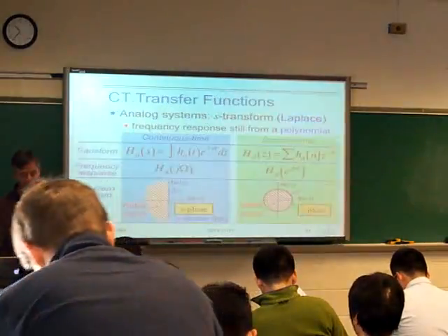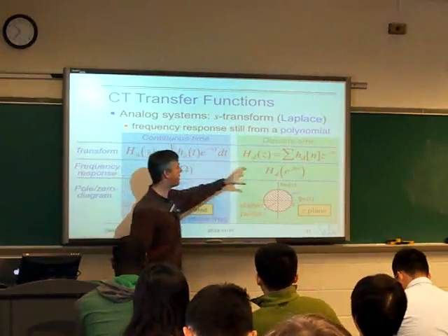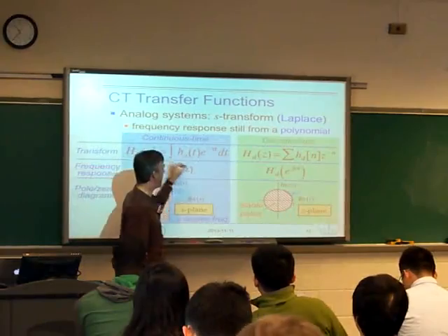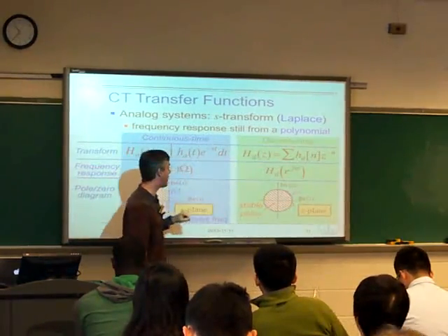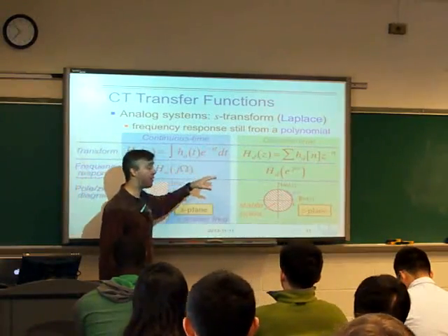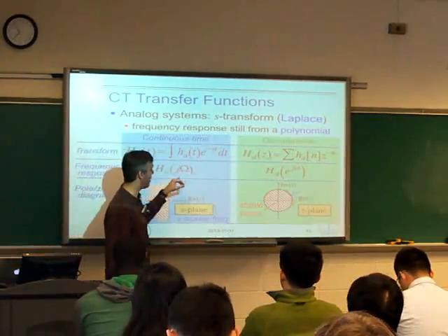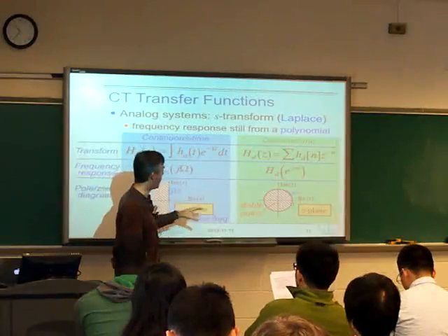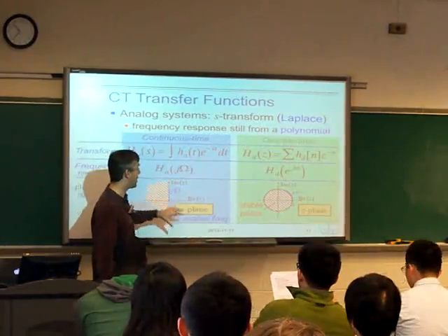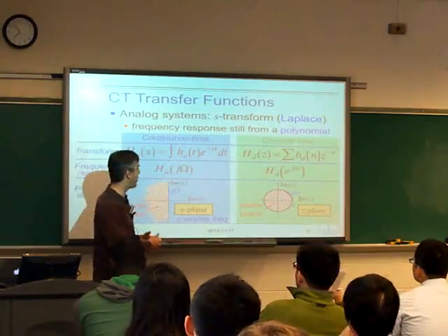The first one, and we talked about the analogies between the continuous time filters and discrete time filters. They both have this transform variable, the S Laplace variable or the Z transform variable, meaning that the systems are described in terms of polynomials on these transform domain variable spaces, and so we can talk about representing those polynomials by their roots, by the poles and zeros in the transform domain, and that's a very quick way of understanding what the filter is doing.